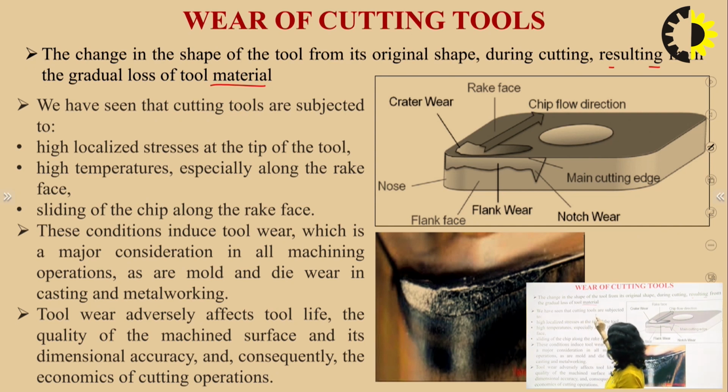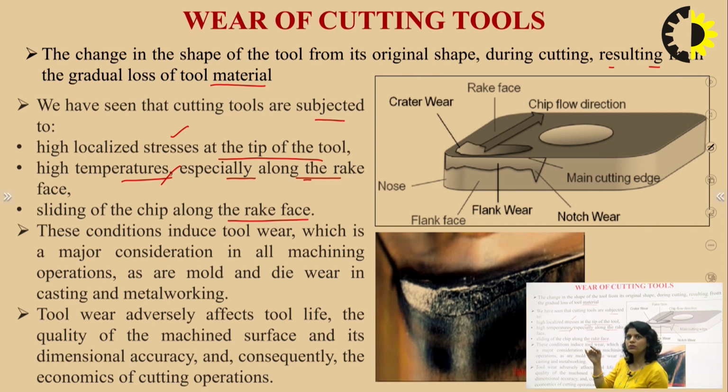We have seen that cutting tools are subjected to high localized stresses at the tip of the tool and high temperature, especially along the rake face, with the chip sliding along the rake face. These are the factors responsible for tool wear. Because of the high stresses, high temperature, and the chip sliding along the rake face where the cutting edge comes in contact with the workpiece, the chances of tool wear are higher there.